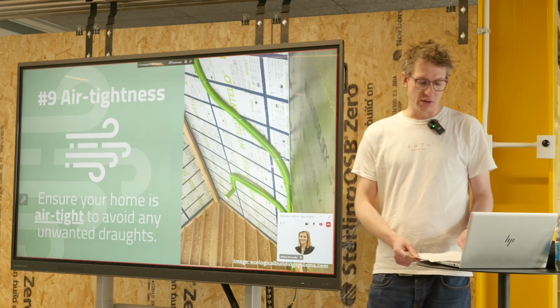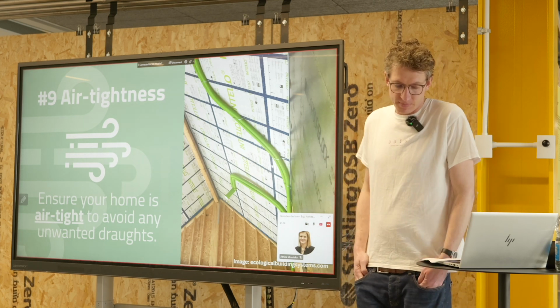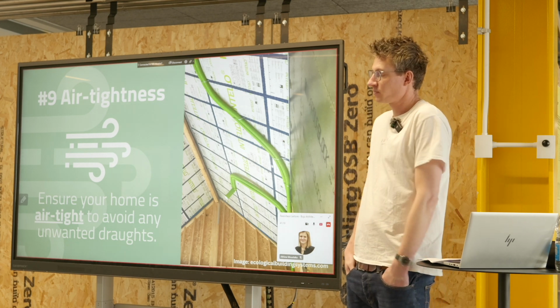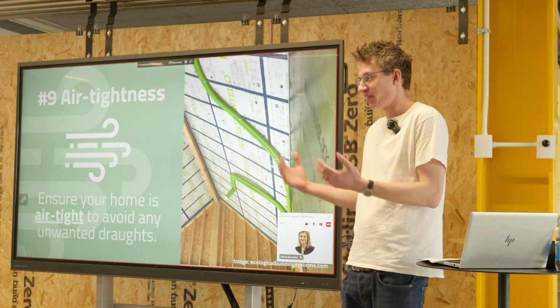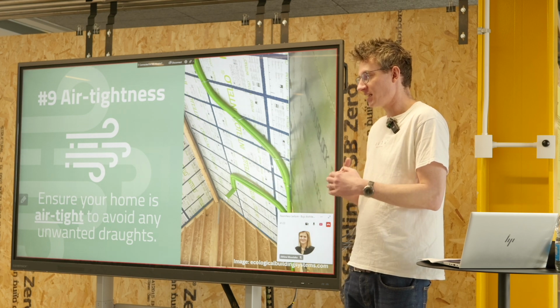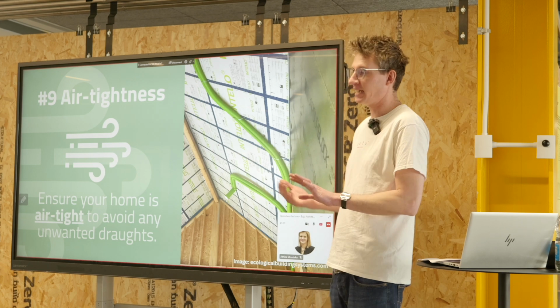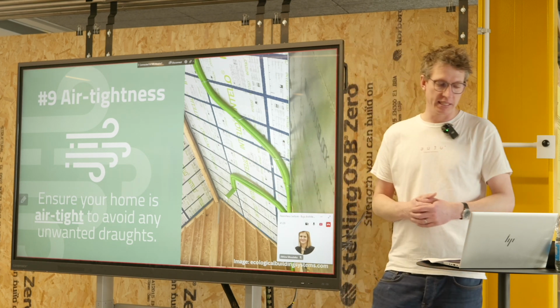And when you're building a Passive House, it's recommended to have 3 airtight tests during construction, rather than waiting to the end and seeing whether it's airtight. Once you've put all the membranes in and you've created the airtight barrier, you test it out to find any leaks before it's obviously covered up.